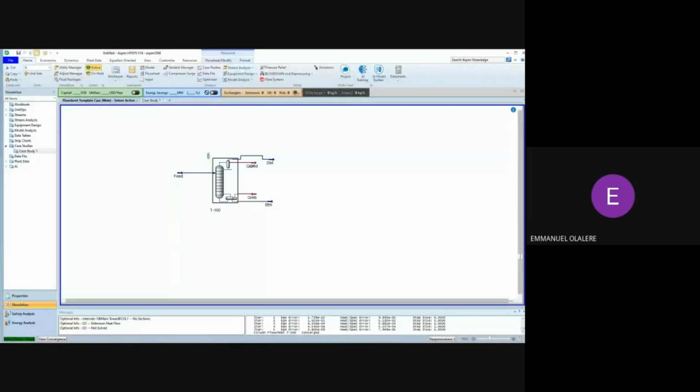Those are the emerging energy sources. So we want to produce hydrogen from hydrocarbon, and these are the reactions that model that process. The key method is the partial oxidation of methane with air, producing hydrogen and carbon oxides via these reactions.